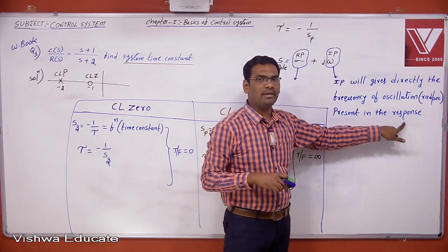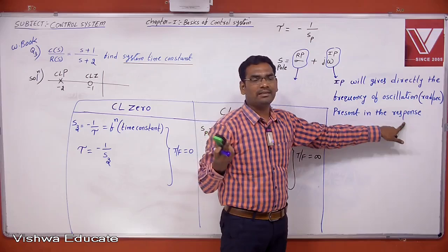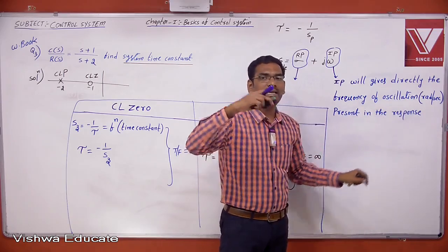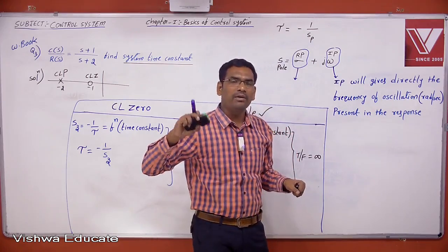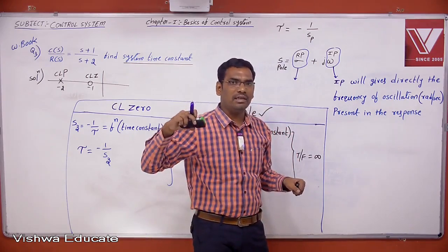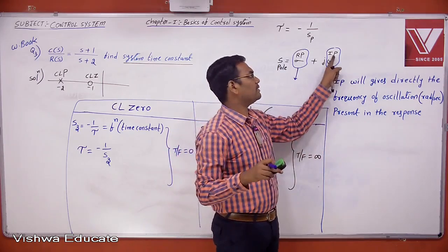What is the meaning of response? After applying the input, you get the output. That output is nothing but this response. In that response, is there any oscillation? Is there any sine wave? Is there any cos wave? Is there any frequency of oscillations? That frequency of oscillation is directly given by this imaginary part.